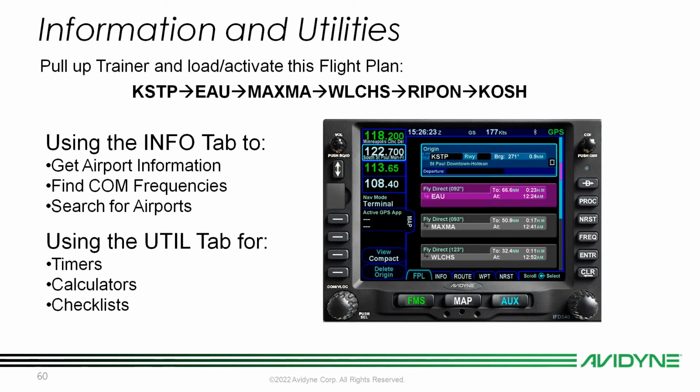What is the purpose in the audio setting standby comm SQ on or off? Is the purpose of the side tone selection to raise or lower volume when SQ is off? So these are digital radios, and there isn't a toggleable squelch, right? With digital radio, squelch either is or it isn't. Okay, so we turn the squelch on, and it's kind of an automatic squelch, and if we have it off, then it's going to give you that hissy feedback that you get if you were to turn that all the way down. Essentially, that's what it is.